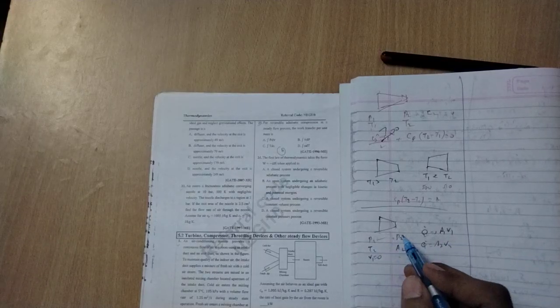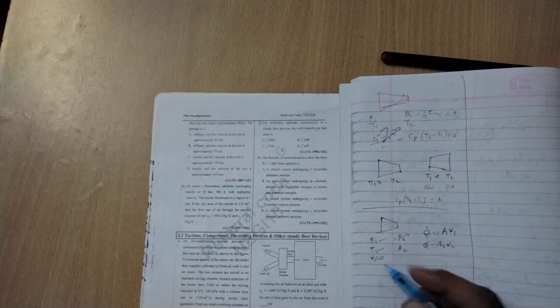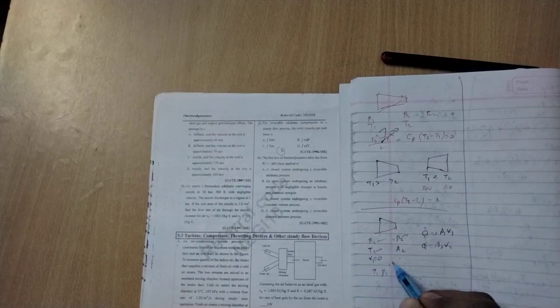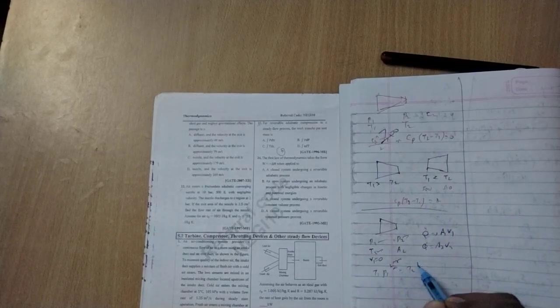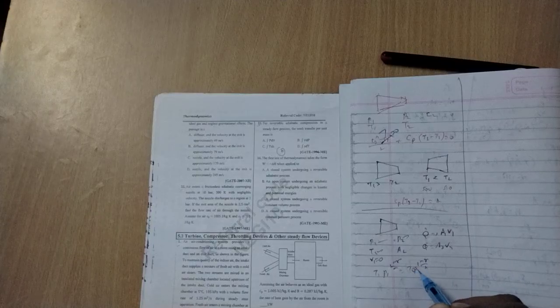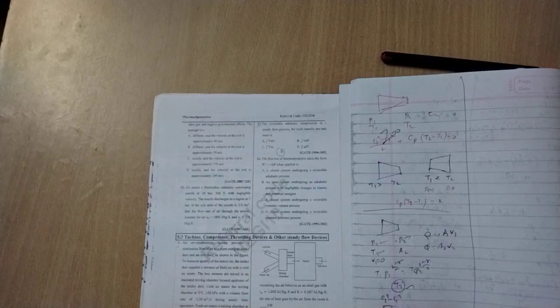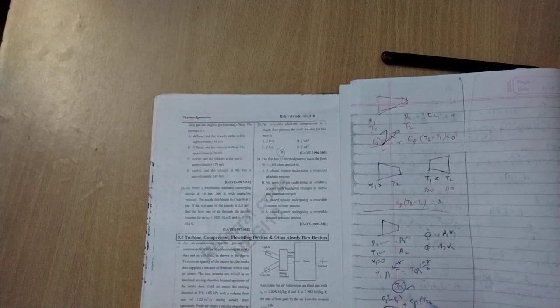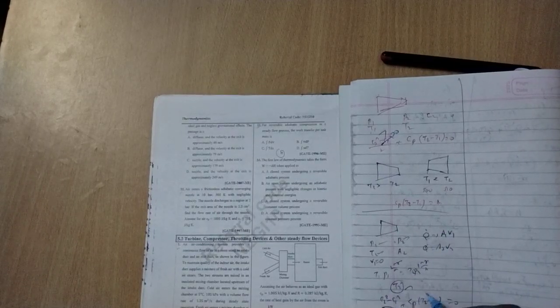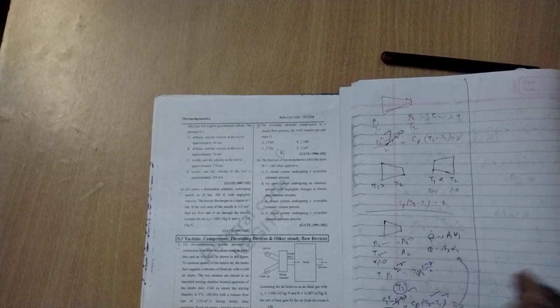You can see P1, P2, T1 are given. As I just told, T1 P1^((1 minus gamma)/gamma) equals T2 P2^((1 minus gamma)/gamma). So calculate T2 here. After calculating, use C2 squared minus C1 squared, divided by 2, plus Cp times (T2 minus T1), equals 0. Put in T2 and T1 and calculate C2, and after calculating, multiply A2 by C2. That's it.